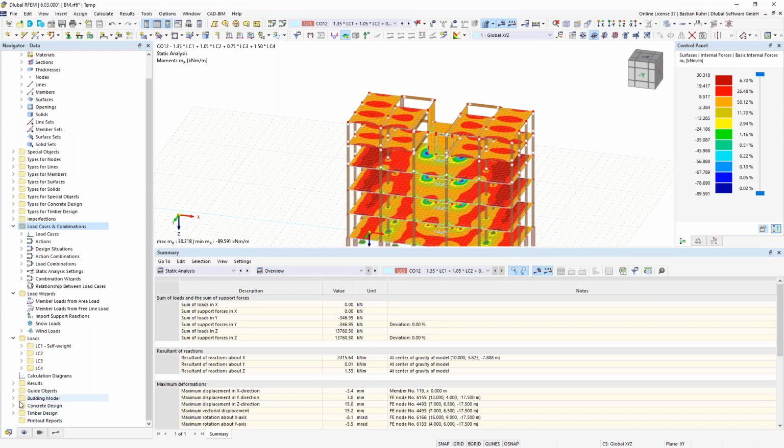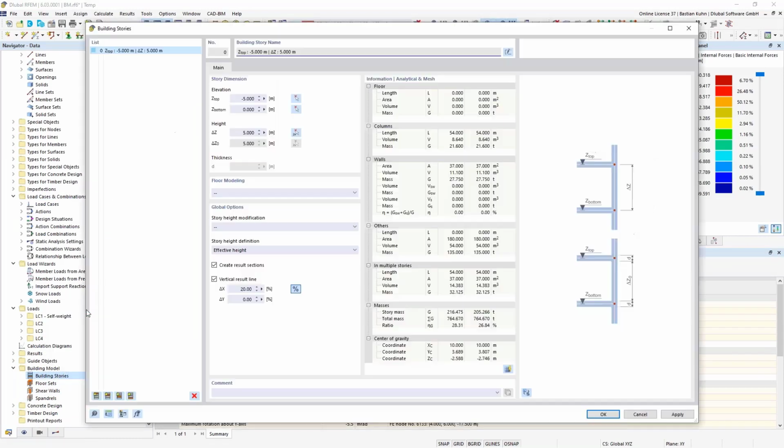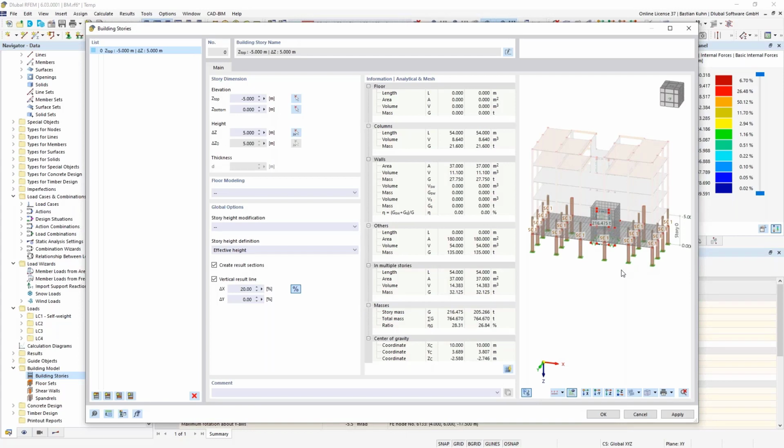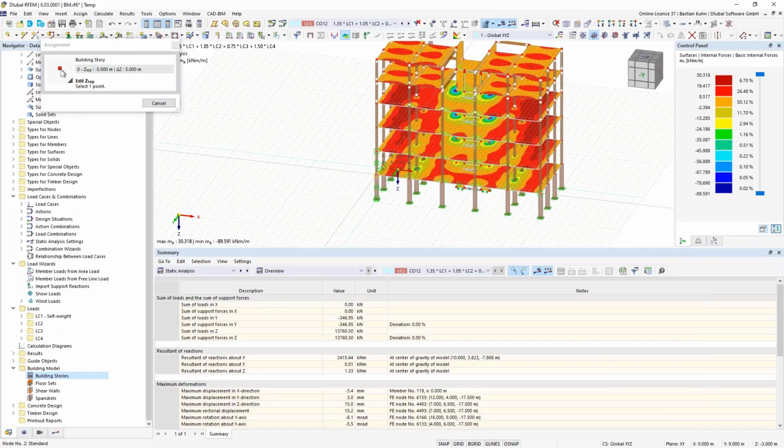Therefore, as we have activated the building model add-on, we will assign building stories. So we go inside in here and define new building stories. There are several ways to generate stories in here, but the usual way probably is to design a building and then assign the stories to it. And that's what I'm showing you here today. The other ways are all described in the manual.